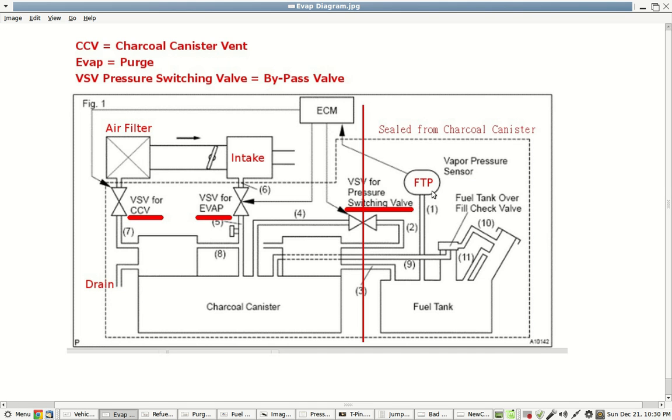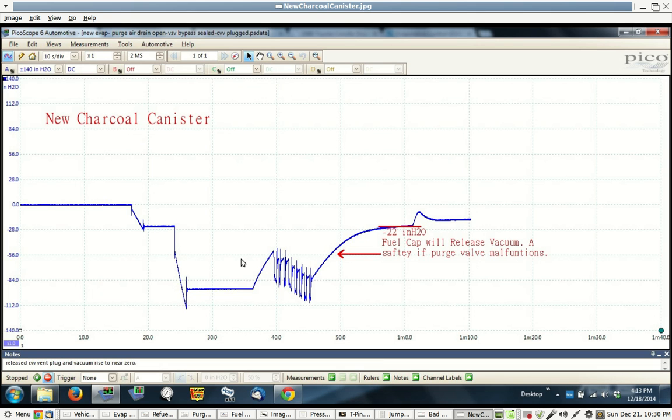The sensor's brand new, but as I run these checks, I make sure that this is responding to what I'm doing. And I'm also watching the laptop screen to make sure. So now I'm going to open this valve. So I manually do that right here, and this opens up the fuel tank, which has pressure on it. So I'm in a slight vacuum, you might say, and then the fuel tank pressure equalizes, and then I add a little more. So I'm hitting the purge valve right here.